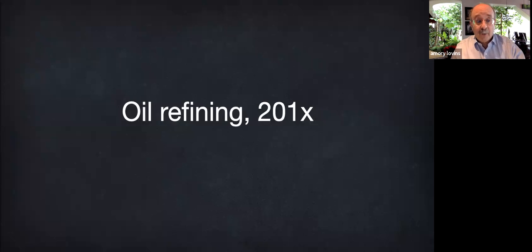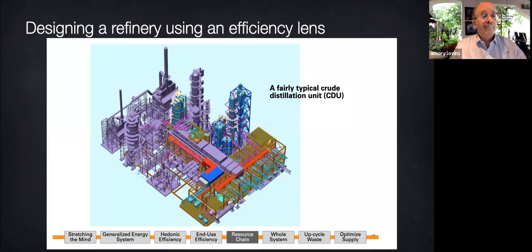Now, our new refinery could thereby probably achieve zero over-refluxing, zero slops, zero flare. These are all important forms of muda to be designed out. You could also use mass-produced miniature or distributed distillers and hydrogen reformers that may be cheaper and surprisingly may be more efficient than centralized ones by eliminating column reboil.